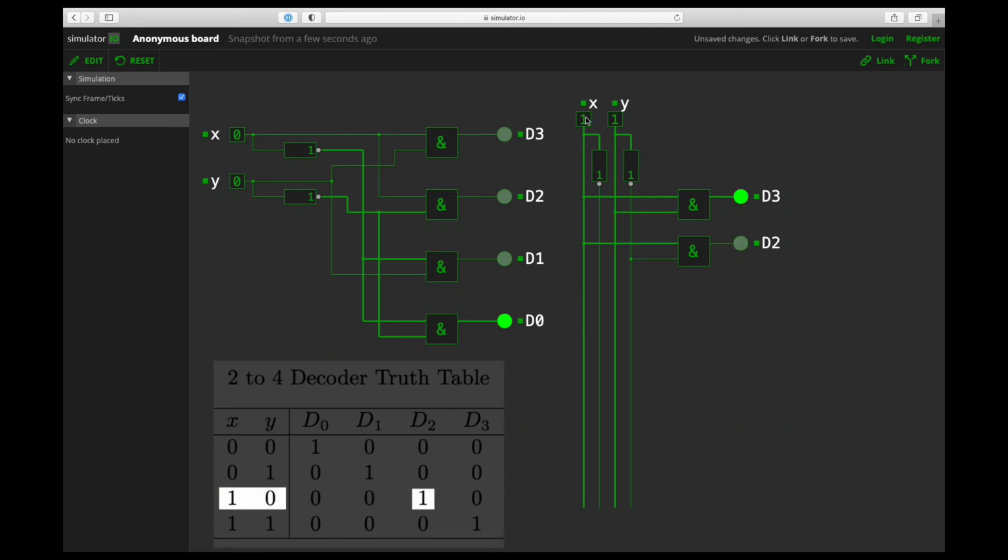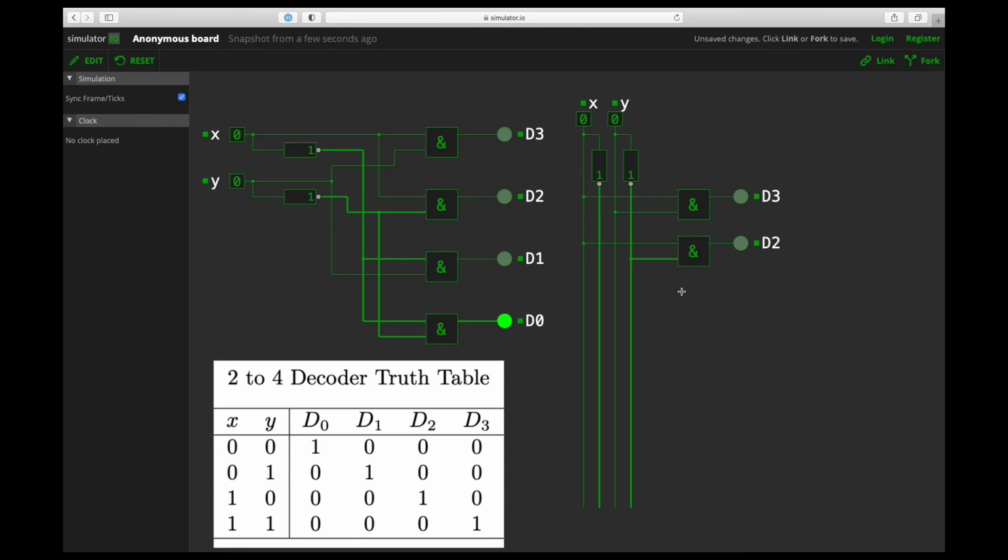And now I've got X and Y both as 1. So that's how you build this from the truth table. You just go back into the truth table, and you can pick your terms from the sum of product form, and then just wire them up accordingly to your inputs. You see, when is your output 1, you look for all the inputs, wire the 1 inputs directly, and you wire the 0 inputs from their negation.